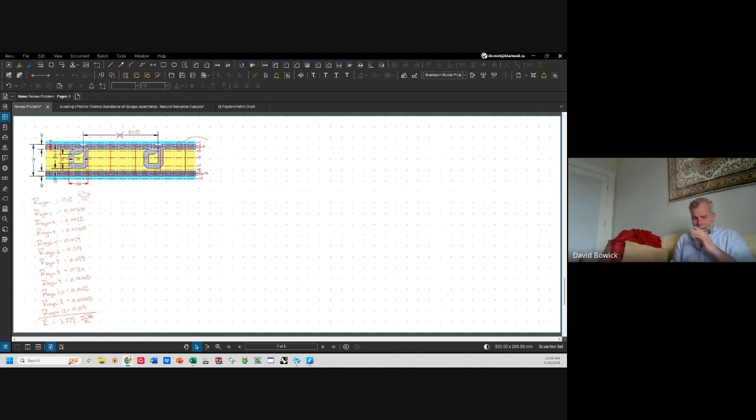If you have very little insulation, there is almost no temperature difference from one side to the other, which makes sense, but the diagram looks funny because your mind thinks it's heat flow. Regardless, your temperature change is proportional to your R value within any given layer. Our task is to figure out the R values of the different layers and apportion the temperature change to those layers proportional to their R value. Okay, let's give it a try.